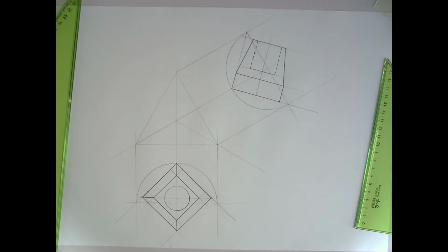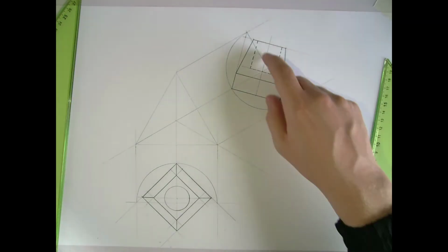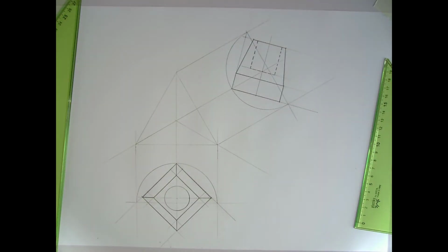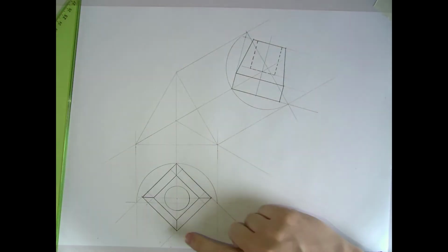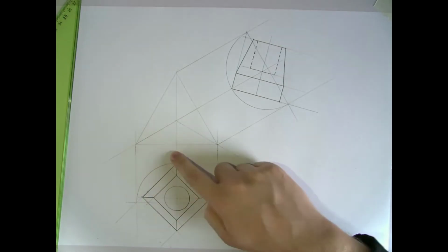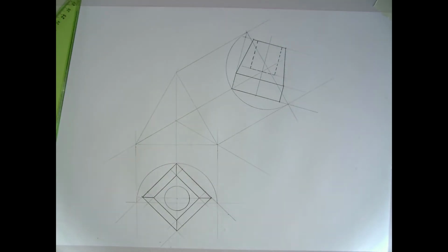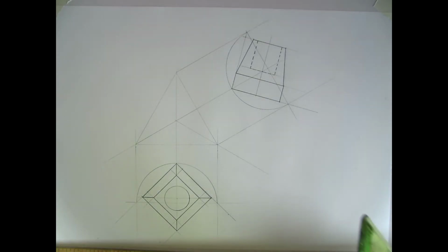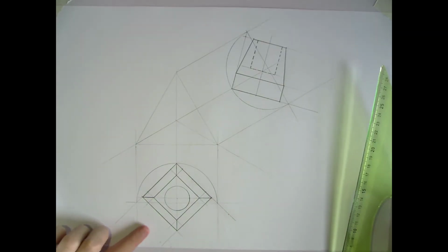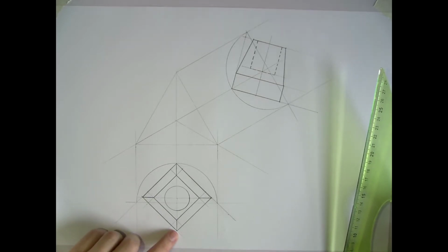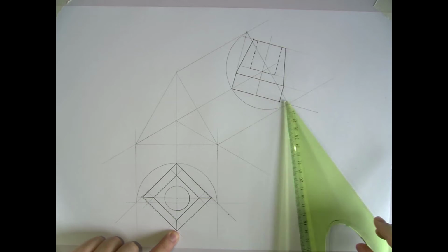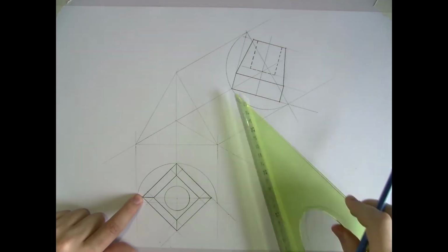So the next part of this is to draw the axonometric projection of the body of the candle holder, so that's taking all of it except the circular hole, the cylindrical hole taken out at the top of it. So we're going to be projecting the same points from this view and this view, locating them in here and then forming our 3D block. So the elevation is essentially looking in this way at our object. So if I have a point here on the right hand side of it, it's going to be the right hand side of it here. If it's the left hand side of it, it's the left hand side of it here.